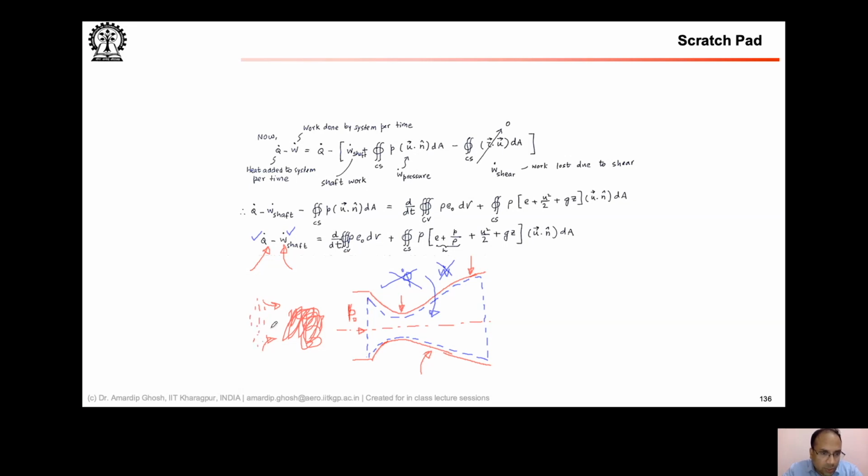In the space shuttle, for example, you have liquid oxygen and gaseous hydrogen shear coaxial injectors. Several hundred of those shear coaxial injectors push liquid oxygen and gaseous hydrogen into the combustor, and the combustion ensures a certain value for P naught and T naught. So combustion creates certain values for P naught and T naught, and then downstream of this, once the combustion has happened, no further combustion is happening.